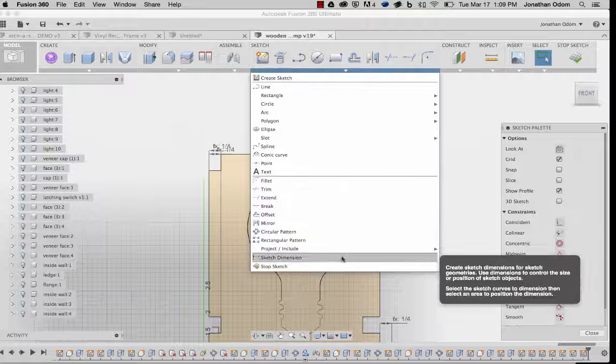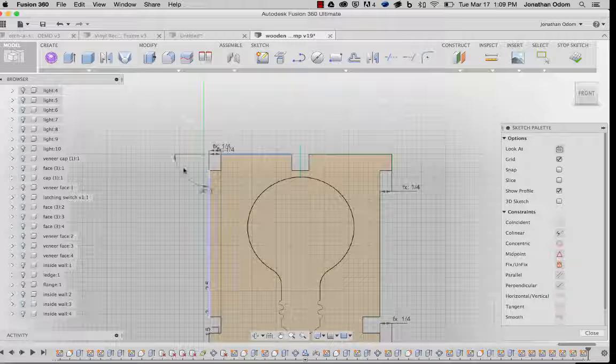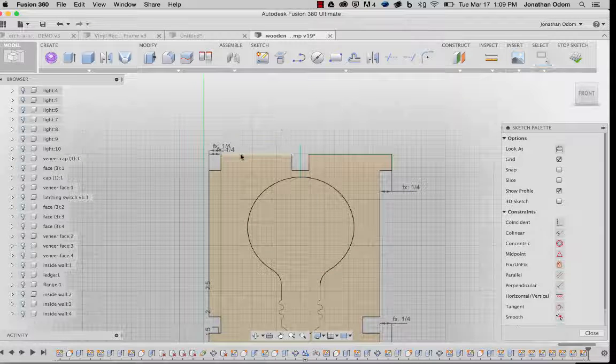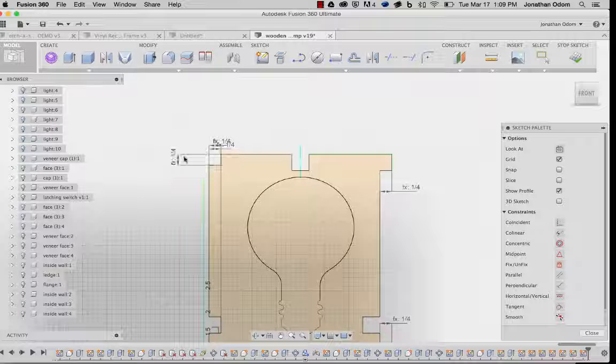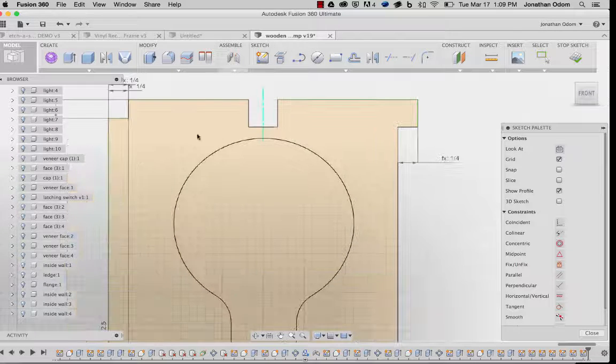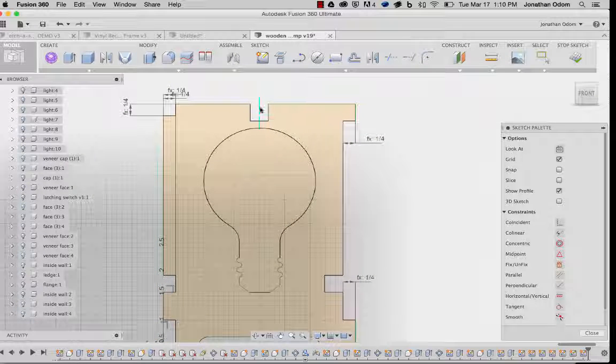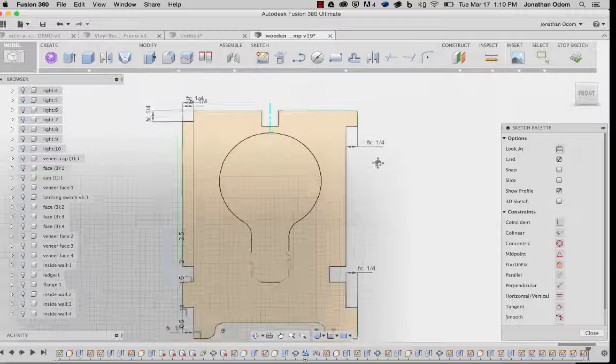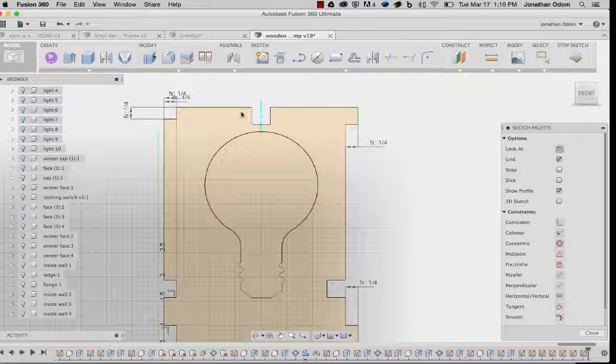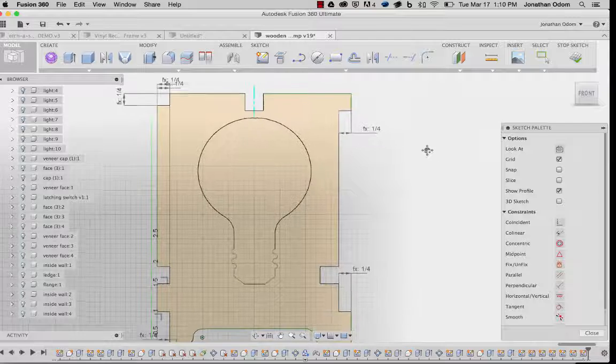So we'll do dimension here. Oops. Right click, repeat. Thick. That should move along. Now this one here, I want the notch up top to be centered on the overall width of the object, and the thickness to adjust along a center line.